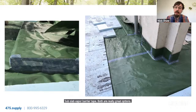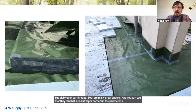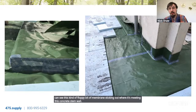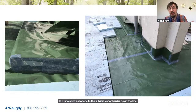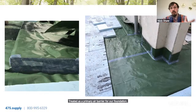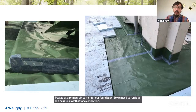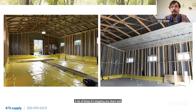And you can see that they ran that subslab vapor barrier up the perimeter a little bit. You can see this floppy bit of membrane sticking out where it's meeting this concrete stem wall. This is to allow us to tape to the subslab vapor barrier down the line, treat it as a primary air barrier for our foundation. So we need to run it up and past to allow that tape connection. A lot of times it's stopping too short and then it's just buried in the concrete.